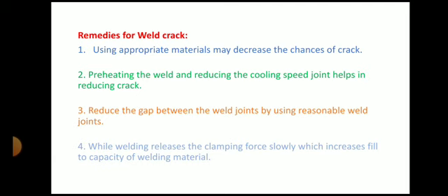Then reduce the gap between the weld joint by using a reasonable weld joint. The gap should be properly maintained between two plates. Then while welding, release the clamping force slowly, which increases the filling capacity of welding material. While performing the welding, if we release the clamping forces slowly, then that will also reduce the residual stresses. So these are the possible remedies for weld crack.